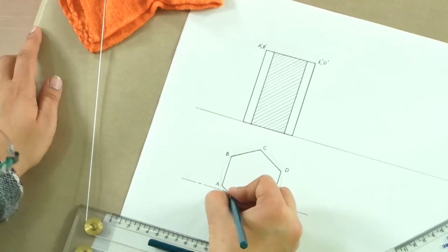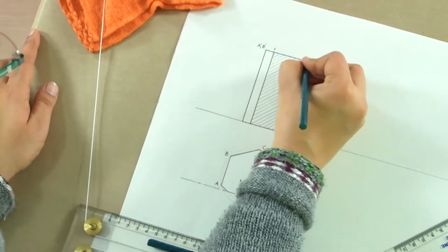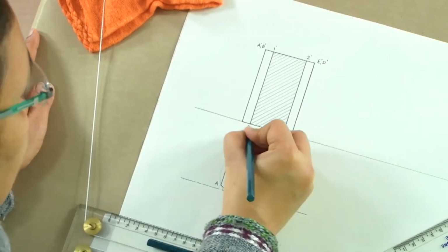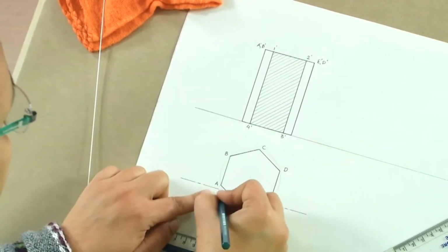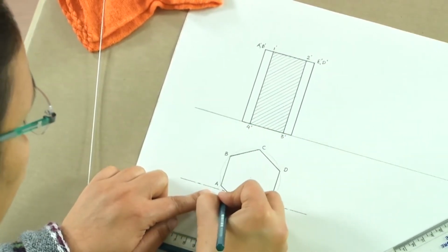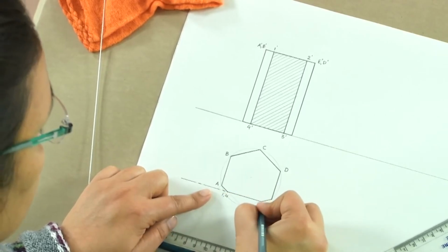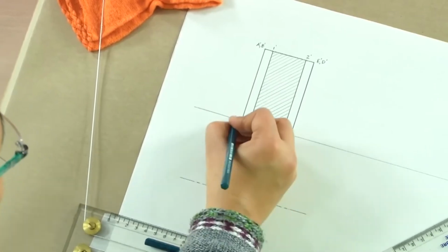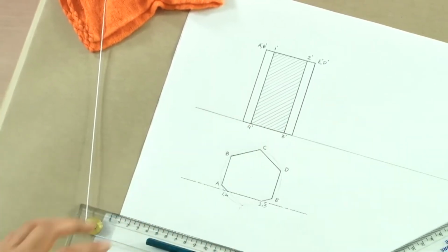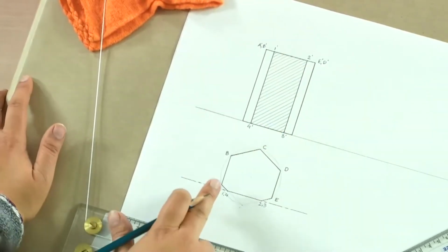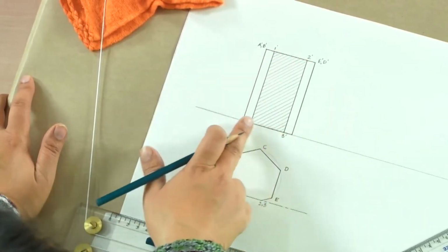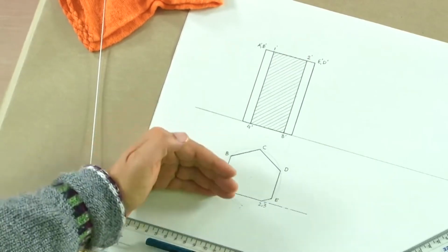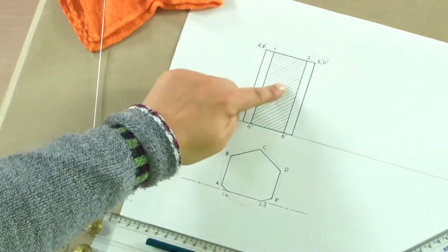You could number it, so we could also number it 1, 2, 3 and 4, and the same thing will be seen here, which will be 1 and 4 and 2 and 3 here, and similarly in the bottom we could also have PQRS, and similarly you could number it. Now also, as we see, this is the true shape of the section. So whatever is being seen here, because the plane is parallel to VP, will also be the true shape of this section.